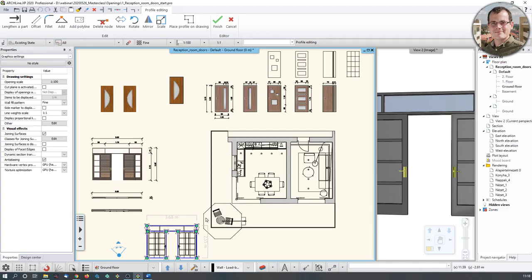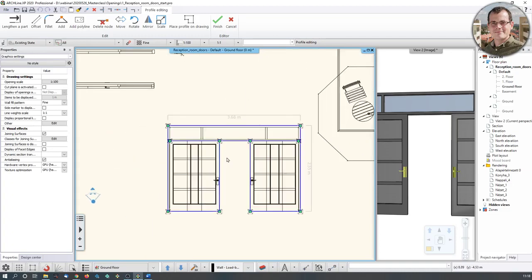And I need to understand what is happening here. So now the software tells me that, based on the current shape of the door, that would be the shape it should be cut out of the wall. Well, it looks good, doesn't it? Well, not really, because if I accept it as it is, then the wall would be inserted here, so it would be like a U-shaped cut.